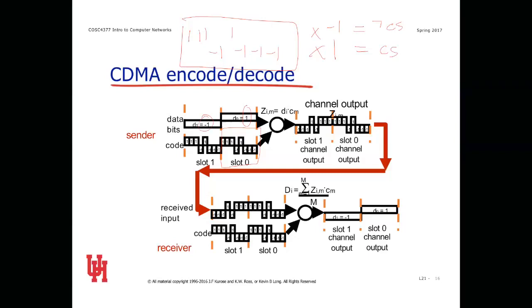All right, so when I want to send the -1, I'm going to flip this upside down, which is what's happening here. And when I want to send a 1, I leave it alone, which is what's happening here. So this is what actually gets transmitted over the wireless carrier. And when I get to the other end, I can suffer a fair amount of error and still pick the signal out. But that's not why we did the chipping sequence. We have other ways of making sure you can encode the signal and get errors out.